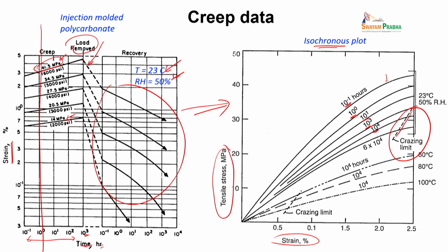So, here we are looking at this dotted line, which basically tells the limit beyond which the material would have actually undergone rupture. There are a few other curves which represent the effect of temperature. All these curves correspond to one single temperature. Here we are talking about a fixed time, but we are changing the temperature. As you can see, when you increase the temperature, the tensile strength of the material actually goes down.